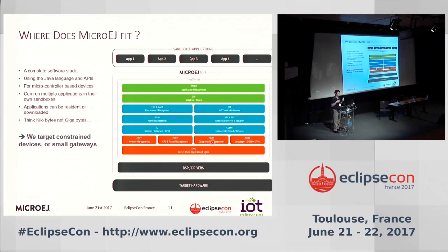It's not just pre-flashed, and it's not a monolithic firmware. It can be updated on the fly, and you can download applications to the device. So for that, you need a component management system. And there are language features like strings and everything related to text and everything related to I/O. And on top of that, we have the file management, the storage management, the I/O stacks, TCP/IP and the socket APIs and TLS. And even on top of that, we also have the MicroEJ framework for doing graphical user interfaces.